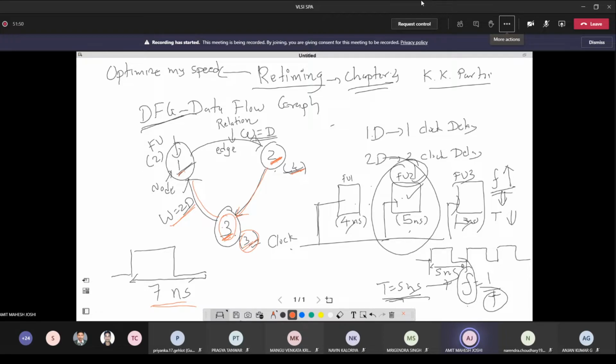So when an edge has a delay, we are talking about an operation which happens at the other end of the edge in a different clock period, not the same one. It is not necessary that it should be completed in this clock; it should be completed after 2 clock periods. So here we do not have to worry about it.